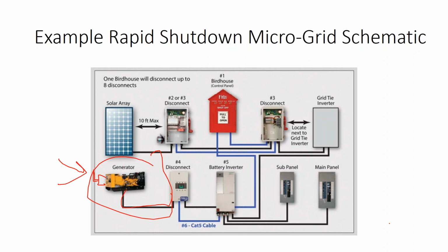But now you might have a battery bank inside the building and a disconnect switch for the solar array outside the building. And so what's the fire department to do? They flick the switch and they think, well, it's already de-energized.